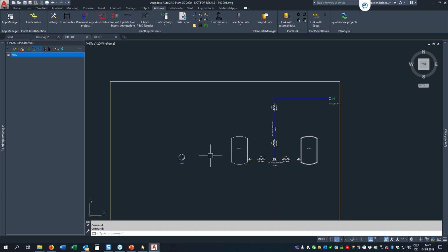One option is that it can also add flanges and gaskets, which are not shown but are there. Then you can create a bill of material from the P&ID which, besides elbows and pipes, contains everything. If you want all these features, it's just a matter of configuration.